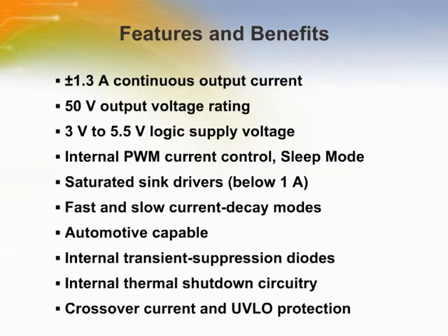Internal circuit protection includes thermal shutdown with hysteresis, transient suppression diodes, and crossover current protection. Special power-up sequencing is not required. The mode input determines whether the pulse width modulated current control circuitry operates in a slow current decay mode or in a fast current decay mode.